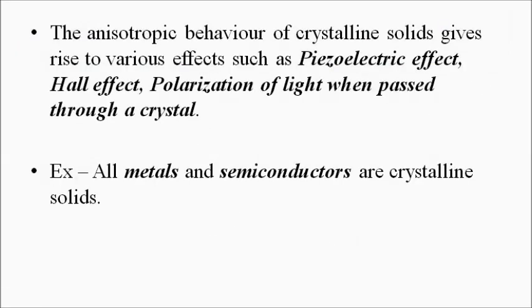And it is this anisotropic behavior of crystalline solids which gives rise to various interesting effects which are used in various engineering and technology applications. For example, the piezoelectric effect, where when a pressure is applied perpendicular to a piezoelectric crystal material, quartz, tourmaline, rochelle salt, whatever, it produces a voltage at the ends of the crystal.